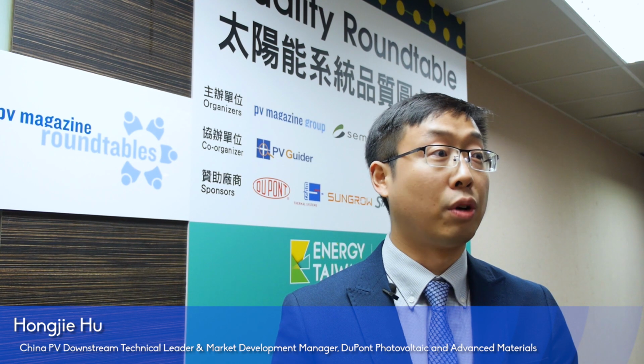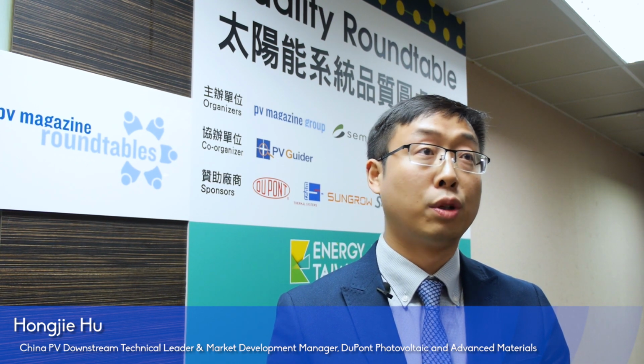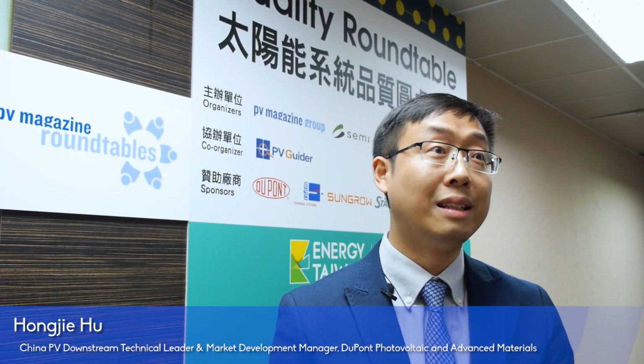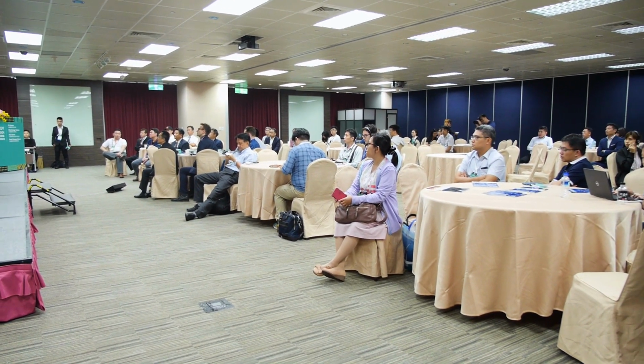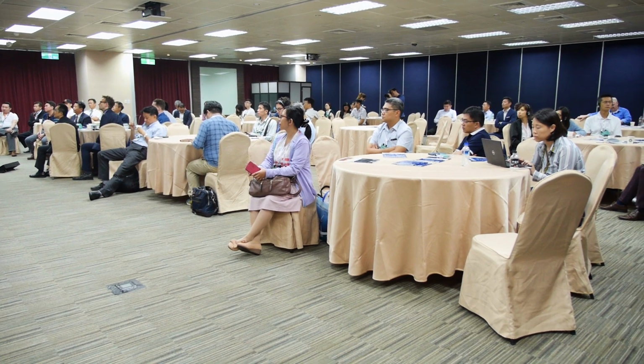For this kind of environmental stress, it requires some special properties for the backsheet: superior durability to UV, very strong mechanical strength, and superior corrosion and chemical resistance. So at this point, the Tedlar-based backsheet can be the best choice for floating PV.